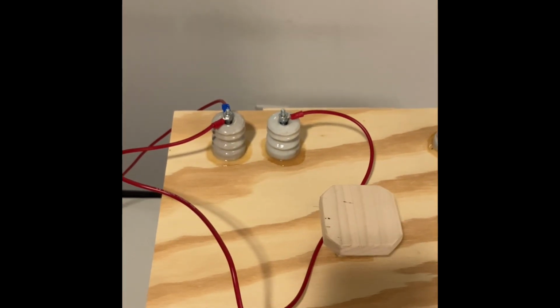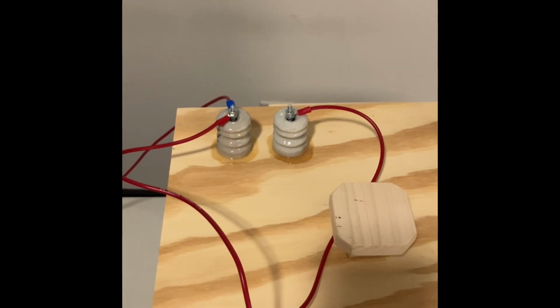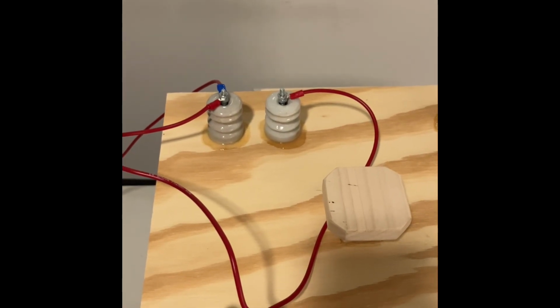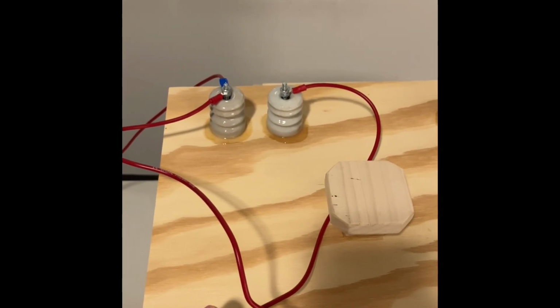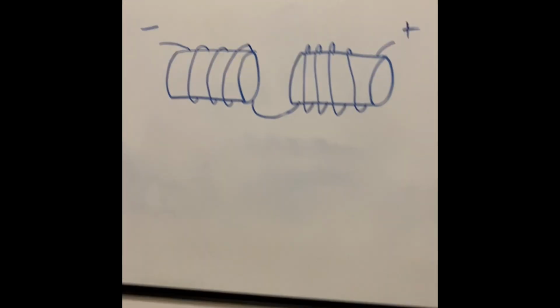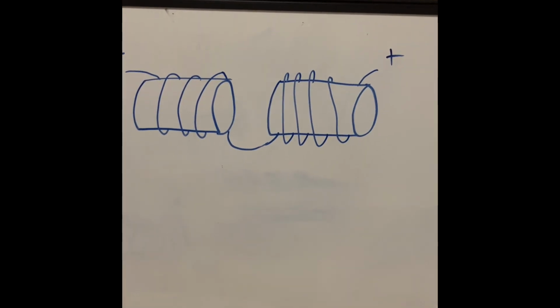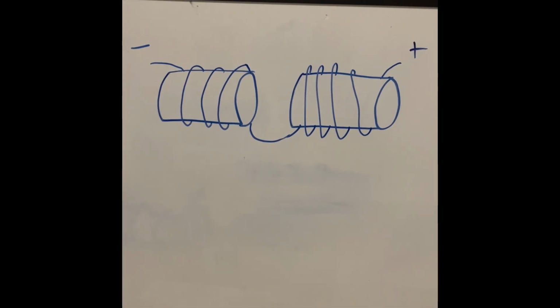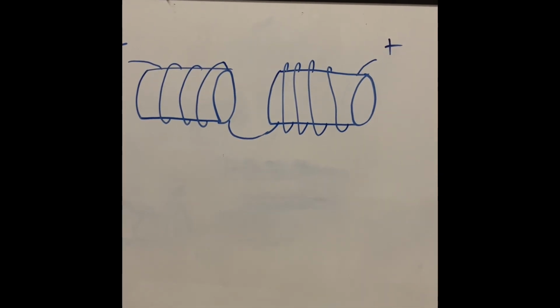This is because if you connect it the other way, when you try to put them in parallel, you get the magnetic fields of each of these primary coils going in the same direction, and the currents that it will induce in the secondary will fight each other and cancel out, and you'll get pretty weak effects. That's what I was doing at first.